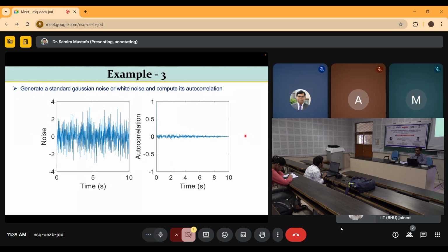So whatever noise, suppose you are first doing filtering, eliminating the noise from the main data, then you calculate the autocorrelation like this. You check whether the autocorrelation function shows something. If there is some autocorrelation, then you cannot use the white noise modeling framework.